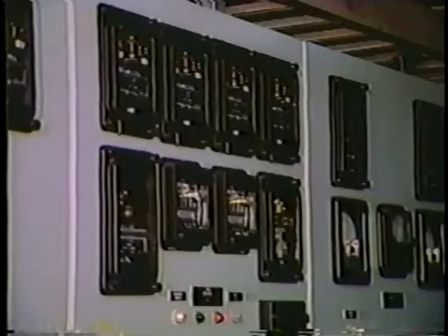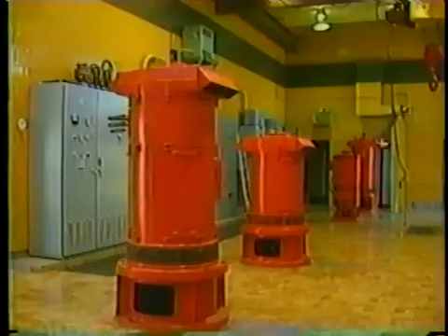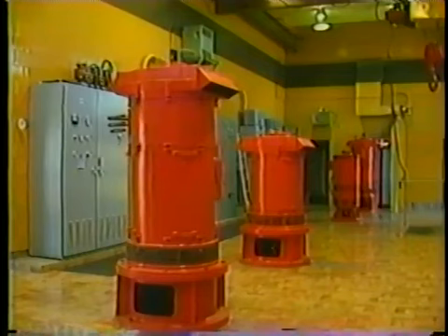Overcurrent relays are widely used throughout the power system, not only for feeder protection, but also for motors in industrial applications and for backup protection in other areas. When applying time overcurrent relays of the electromechanical type, 2 points that must be considered are over travel and reset time.